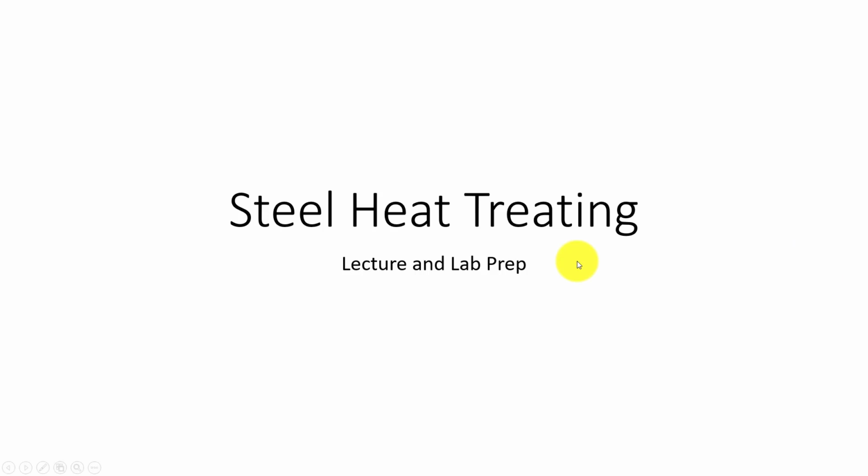Okay, in this session, guys, we're going to be talking about steel heat treating. And in this lab, you're going to be working with two different alloys of steel. One's going to be an alloy steel, probably 4140, typically we like to work with, and the other steel is going to be a tool steel, and we're probably going to work with A2, which is air hardening tool steel.